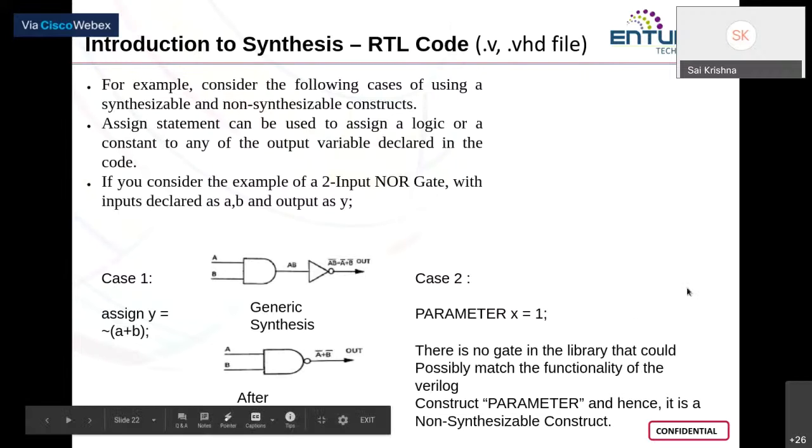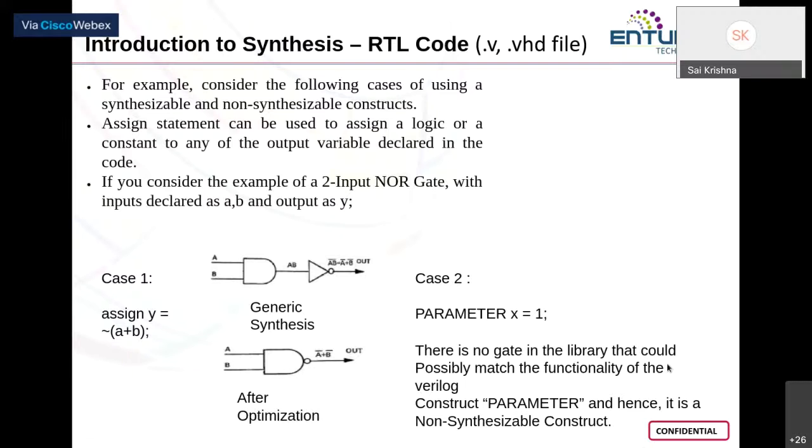So as you can see here, this is an example to show you the non-synthesizable constructs. In case one, you can see that we have y is equal to negation of a plus b.